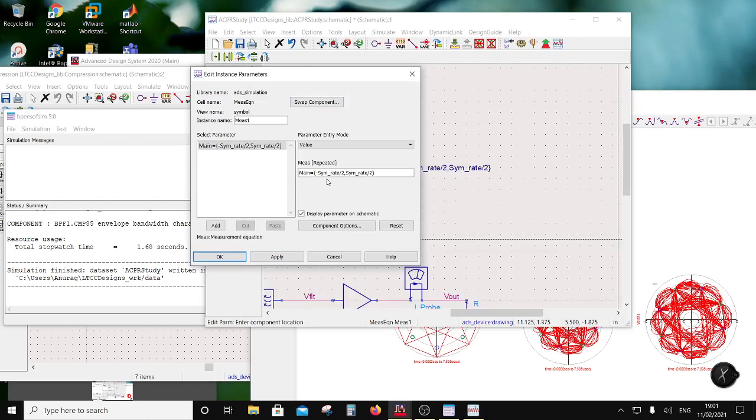So I have to go to the other channel. The other channel, let's say, is going to be upper. That upper is going to be equal to main plus, so the entire spectrum is going to be shifted up by symbol rate, and I will provide an excess bandwidth which is 1.35 now, right?